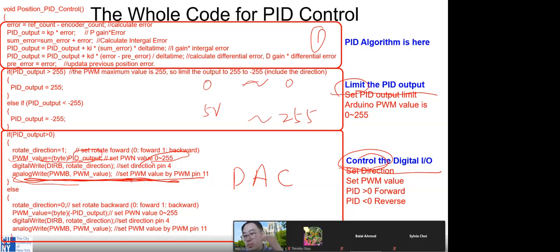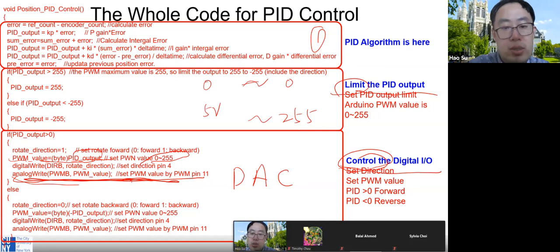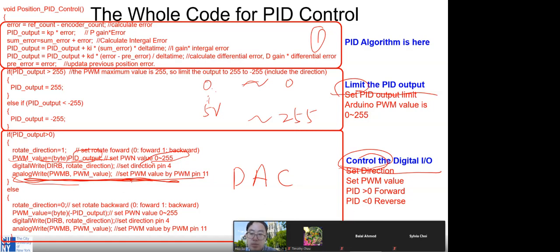So it's discretized from 0 to 255, all integers. In the last lab, it was shown that 5 volts was a value of 1023, and you were supposed to figure out what, let's say, 3.3 volts would have been, and what kind of value would be given.